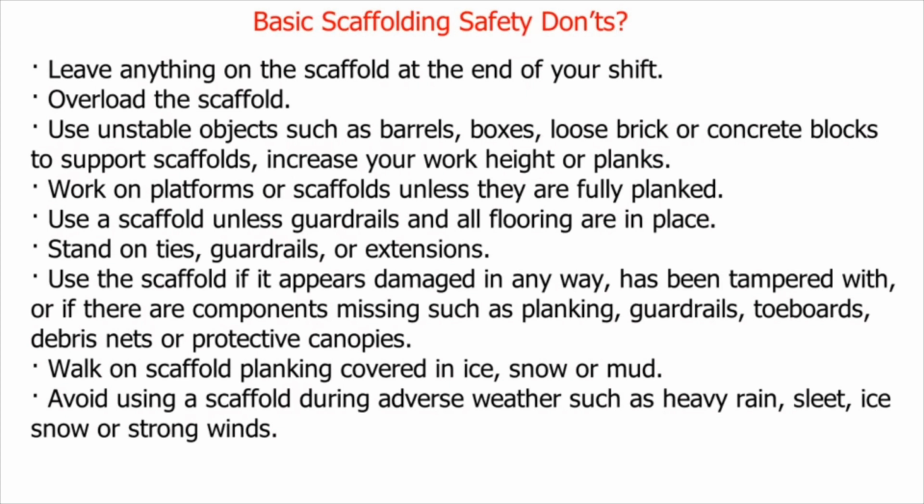Work on platforms or scaffolds unless they are fully planked. Use a scaffold unless guardrails and all flooring are in place. Stand on ties, guardrails, or extensions. Use the scaffold if it appears damaged in any way, has been tampered with, or if there are components missing such as planking, guardrails, toe boards, debris nets or protective canopies.